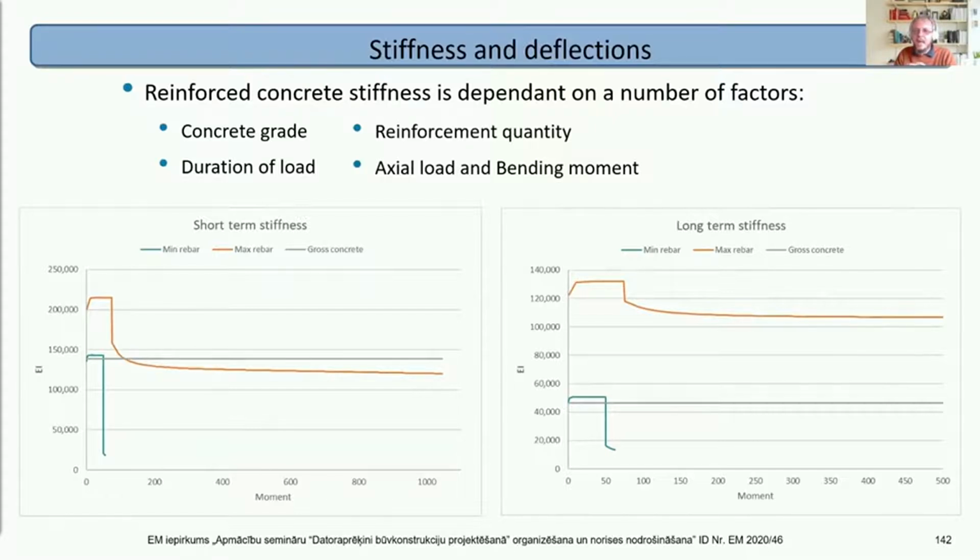A lot of it is dependent on how detailed you need the deflection to be, because obviously what we didn't cover in here was variation on the section size, the tolerances. When they're pouring the concrete on site, the thickness of the slab or beam is dependent on how much concrete they pour in, and it can be a little bit variable.